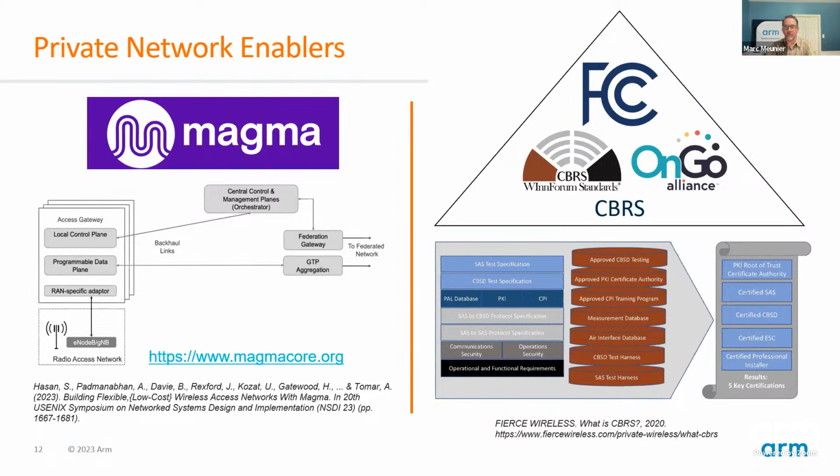All that you need is for that UE device or the radio to be validated on this channel. So it's not like you need brand new hardware that just communicates on CBRS. You can use standard off-the-shelf radios that just have that checkbox, qualified by the FCC to run in the CBRS band, and then you're up and running.